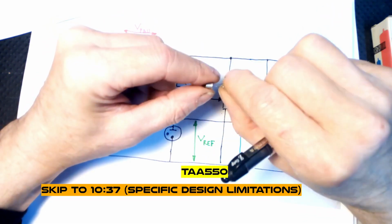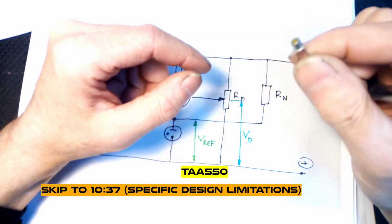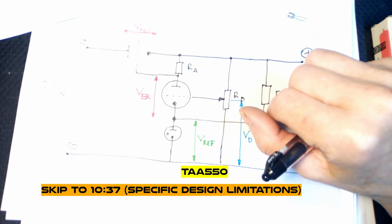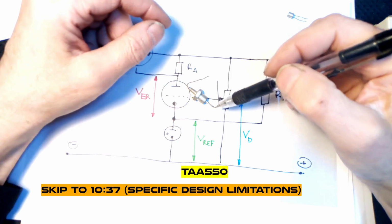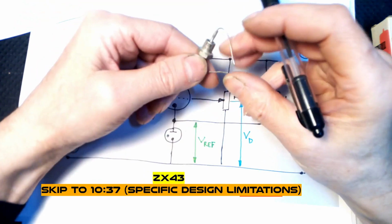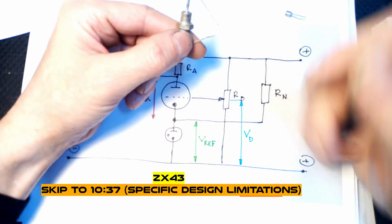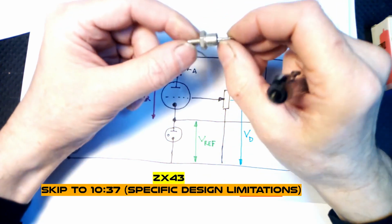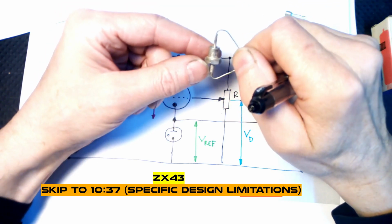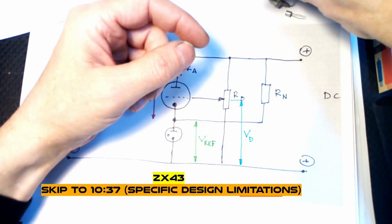It's sold under many names. It's not a Zener diode, this is an IC inside. Or we can use a Zener diode, this is what I have. It's a ZX43, which means 43 volts. With a Zener diode there is a kind of problem, because they require a bigger current for working properly.